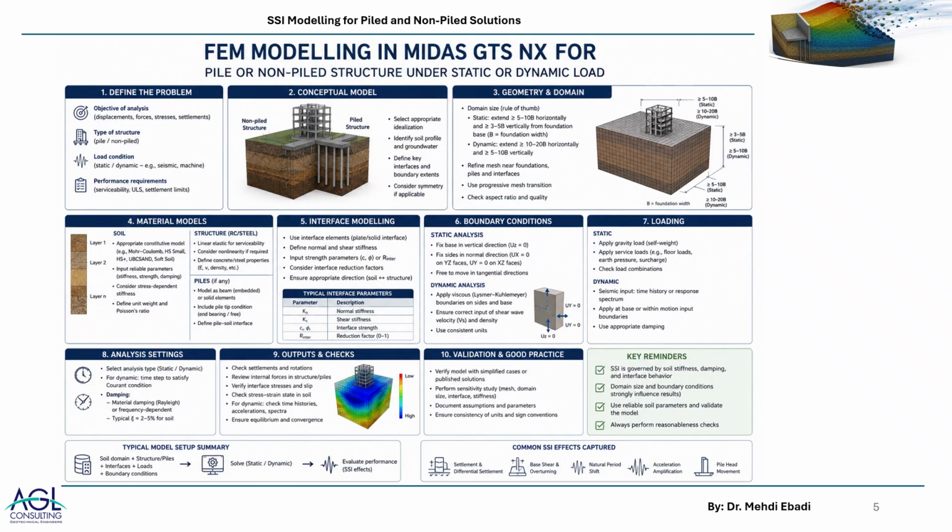For example, if you have a foundation sitting on a layer or two layers of soil over rock, the stratigraphy is horizontal, there is no complexity, and you are just analyzing this against levels of pressure where you don't expect yielding, well, if you want to use simple models, even linear elastic would give you good results for these projects.